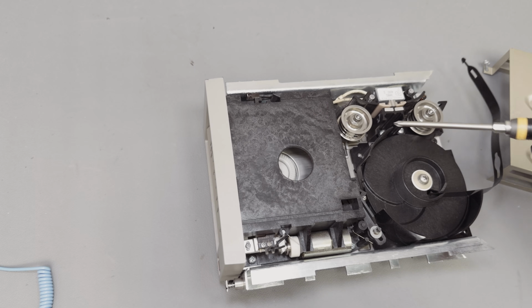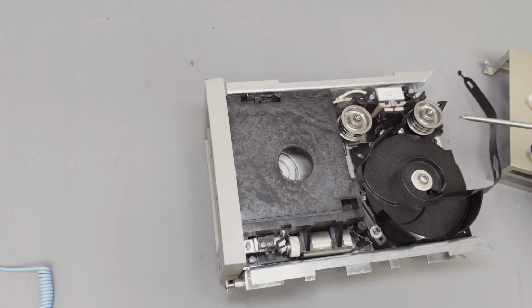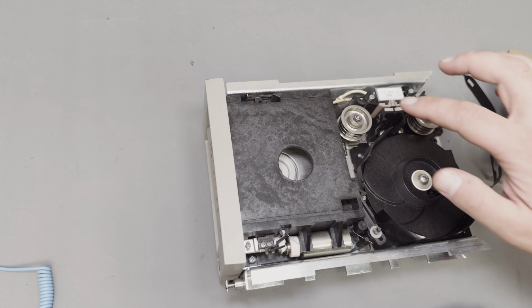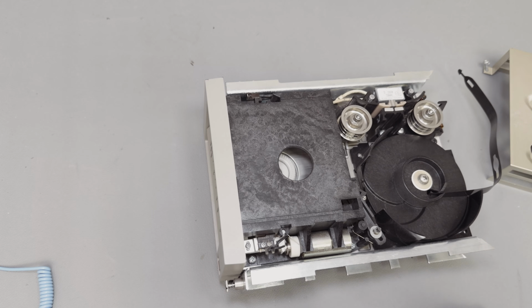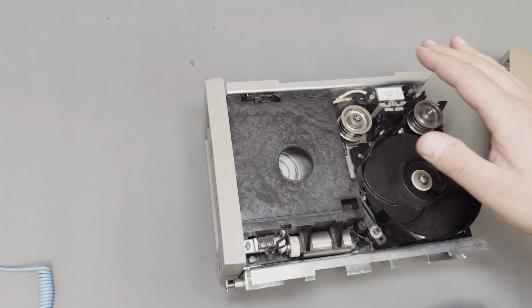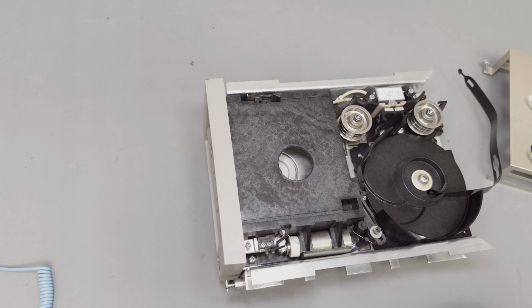And there's a bit of dust here on these metal wheels, also on this plastic part, so first I will vacuum it, and then I have a special cleaner for magnetic heads, and will clean the read-write head, but without any pressure, because with pressure you maybe destroy the head, so it's quite fragile. After that I will put everything together, build this tape drive into the VAX, put the cover back on, and then turn on the machine and check if the tape drive will work.